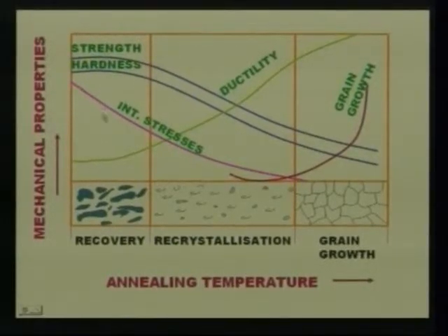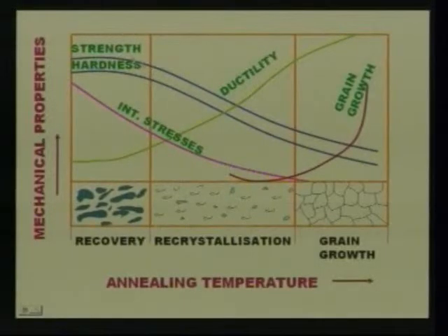You see in recovery the strength and hardness are high, whereas strength and hardness slowly decrease in recrystallization and also in grain growth. The internal stresses are high in recovery, and slowly decrease in recrystallization and grain growth. And ductility is low in recovery, but slowly increases in recrystallization and also in grain growth.